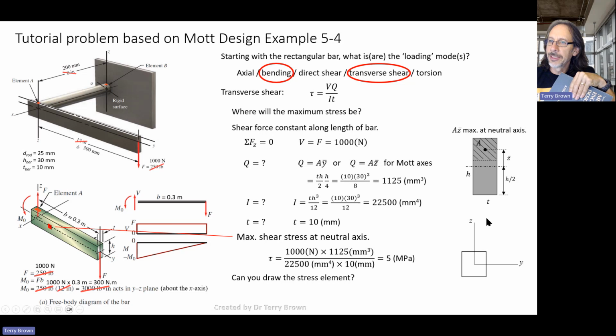We've got the same axes as before because we're looking from the side. So we've got Y and Z. Right, we've got this force pushing down here. So we're going to get the shear stress in that direction on that side of the element. Okay. And then because it's in equilibrium, the whole square must be in equilibrium.